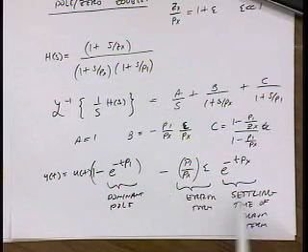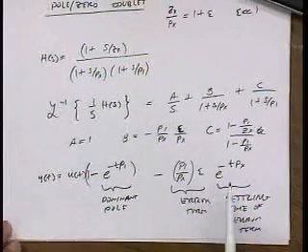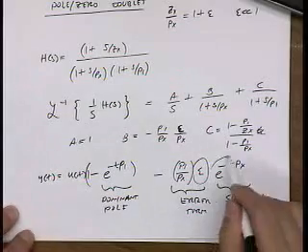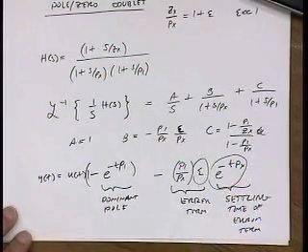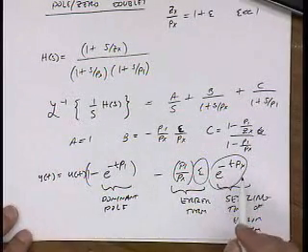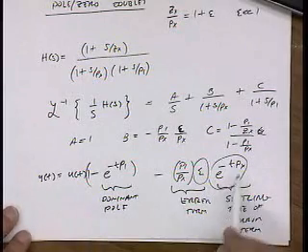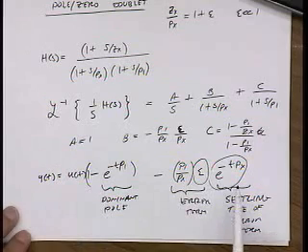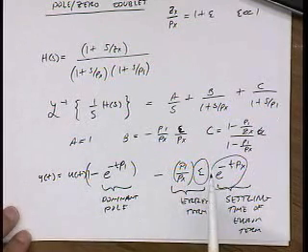So again, I think I screwed up the algebra, but the idea is that you're going to get a term proportional to epsilon and a term proportional to e to the minus t over px, where px is the time constant of that pole zero doublet. And so your overall error, if you're not careful, could be determined by this term.